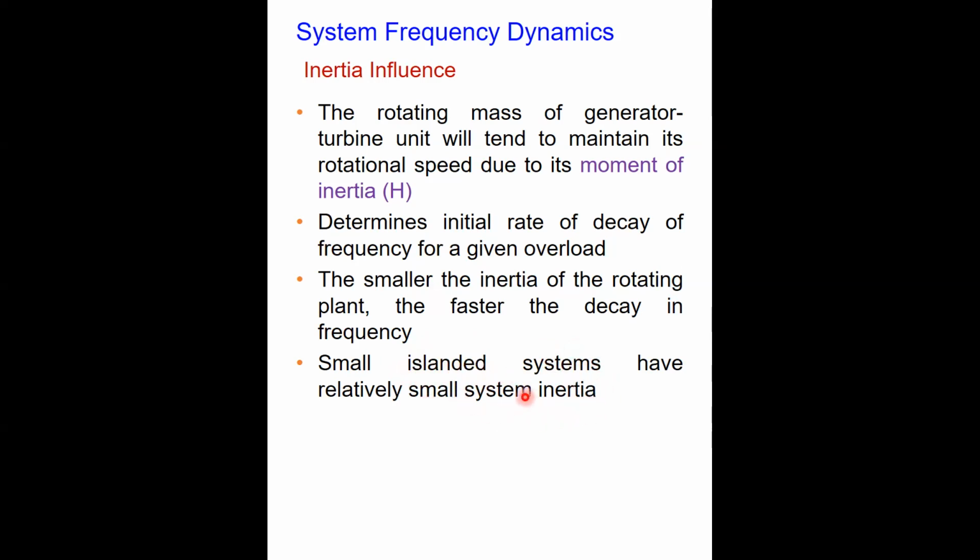In the small inertia system, the decay in the frequency could be more, and thus it is important that it will be much more challenging to obtain the frequency regulation for an islanded system because the system inertia is low, as compared to the interconnected system here.